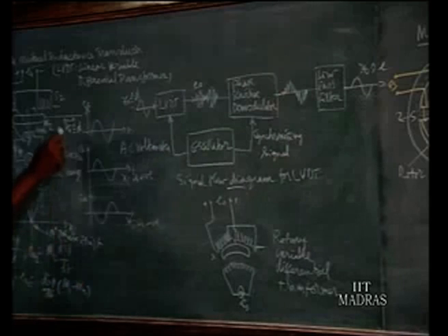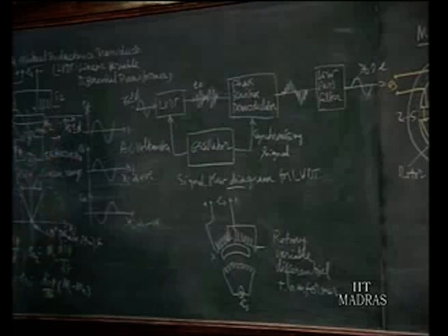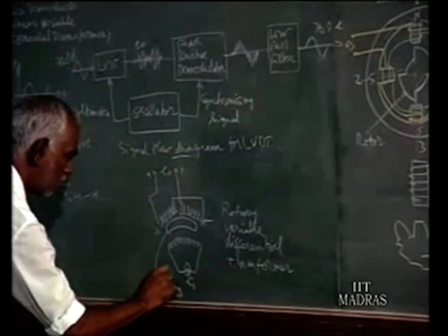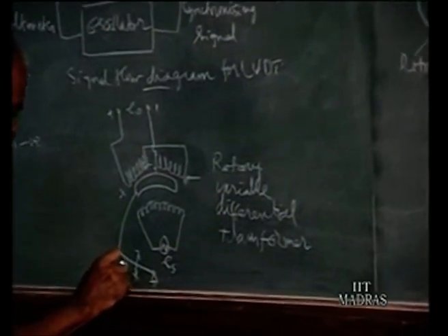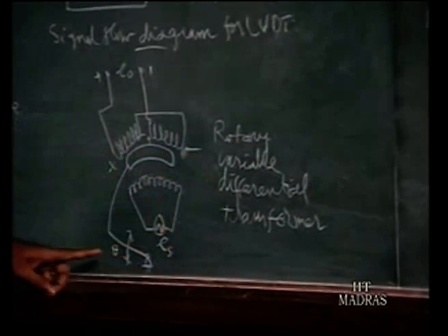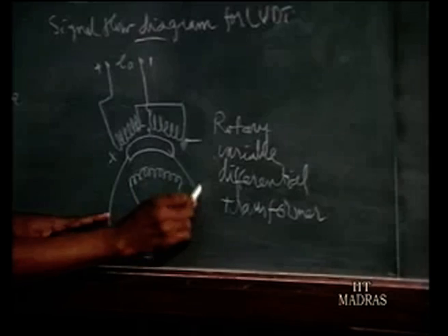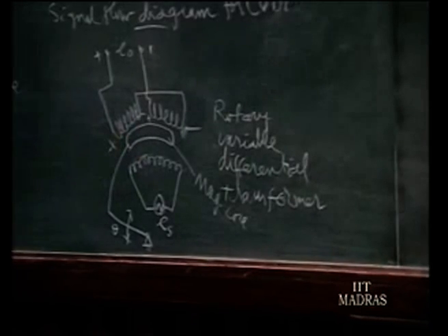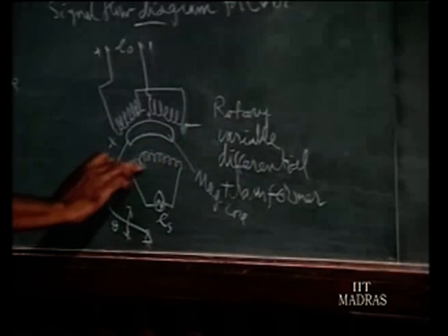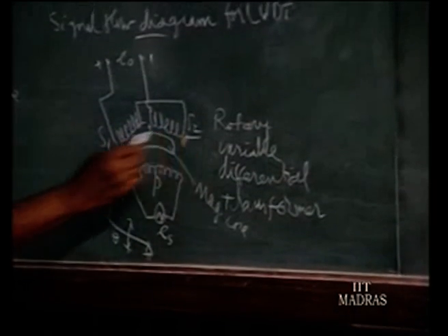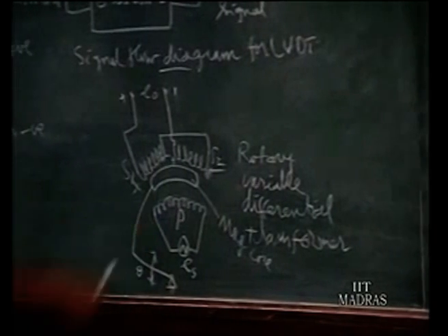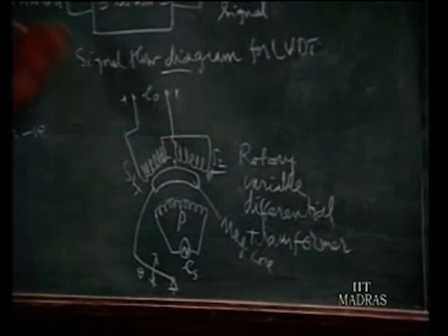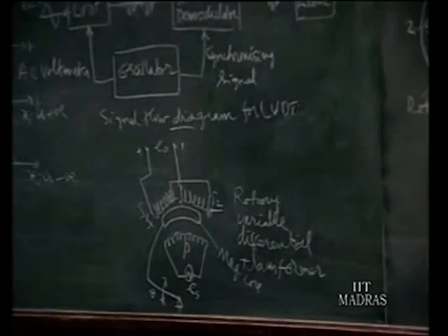So this is for linear motion, along a line; Xi is the displacement along a line. When it is pivoted, you can give rotary motion also. Hence it is called a rotary variable differential transformer. We give this angular rotation to the magnetic core, with the same construction made along an arc. So this is the primary coil P, this is S1, this is S2, and it functions the same way. But here the angular rotation is given to the transformer, hence it is called rotary variable. Otherwise the functioning is on the same principle as that one. So that is regarding the mutual inductance.